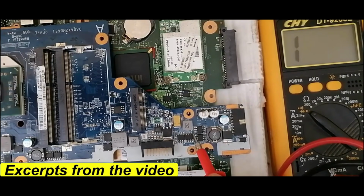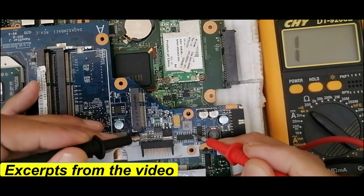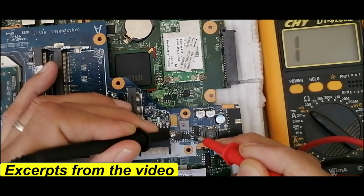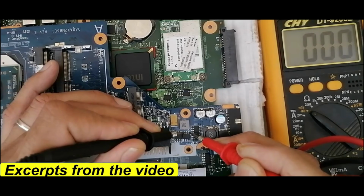Let's take this MOSFET. Do you see the white dot here? It means this is pin number 1, so pins 1, 2, 3 are source. We should find continuity here. Let's check. I will put one probe on pin number 1 and the other probe on pin number 2. We get continuity in the multimeter and a buzzer.